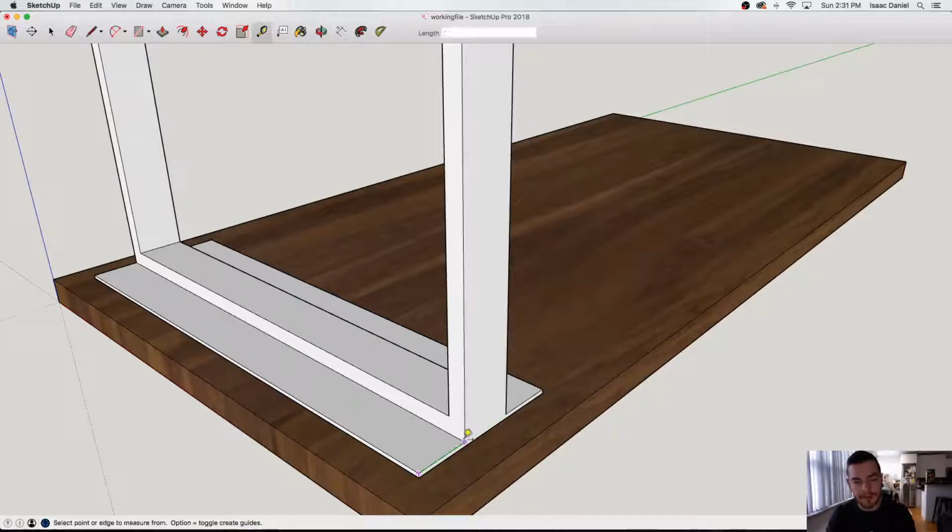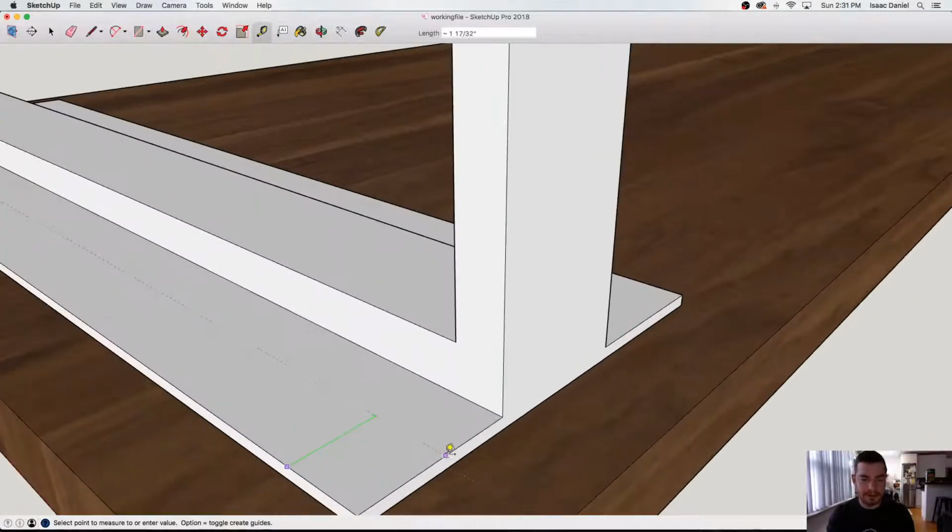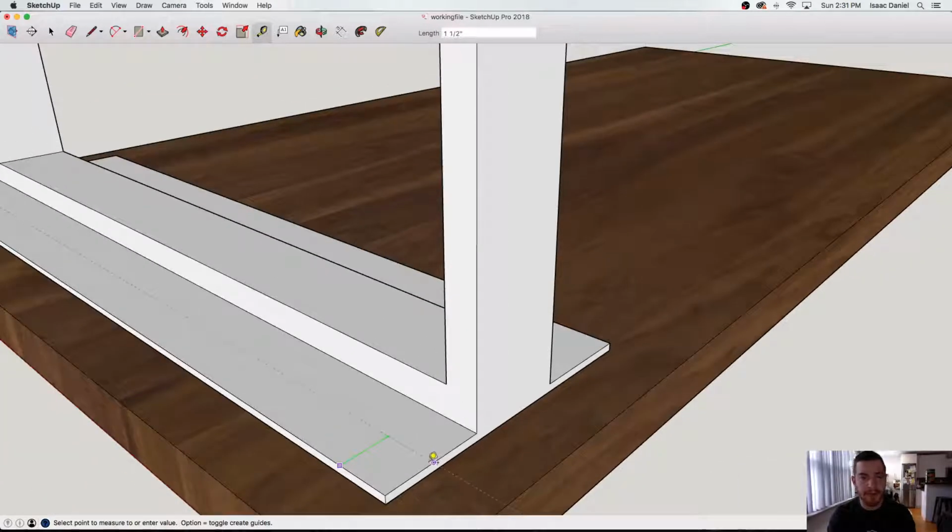The reason for that is if we're using a 3-inch tube, you want a decent amount of space that you could fit screw holes or slotted holes in here. So SketchUp's pretty good. It'll snap to points. So if there's a midpoint in this group, SketchUp will snap to it. So the midpoint is 1.5 inches. Do the same thing on the other side, 1.5 inches.